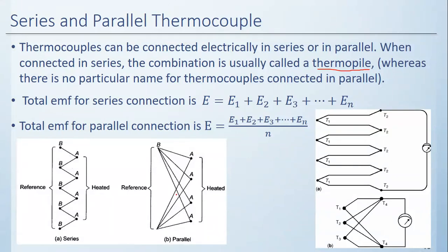Okay. Now, the two figures demonstrate the same. Here in figure 1, you have a series of thermocouples. See, the thermocouple 1 is connected from B to A. The thermocouple 2 is connected from the end of A. Okay, so like this they are connected in series.